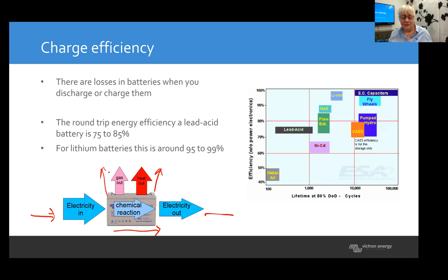If it goes wrong, instead of water vapor, it starts doing electrolysis. So you start to get oxygen and hydrogen, and that's explosive. That's also why lead acid batteries are potentially dangerous, far more than lithium, in my opinion. A lot of people don't know what can go wrong with lead acid batteries. A lot can go really badly wrong.